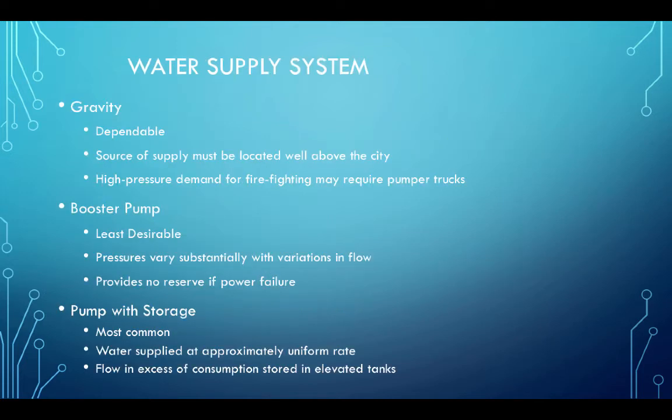So water supply systems can be gravity-fed, booster pumped, or pumped with storage. Gravity is desired because it's dependable. It requires that the source of supply is located quite a vertical distance above the city, and high pressure demand for firefighting may require pumping trucks.